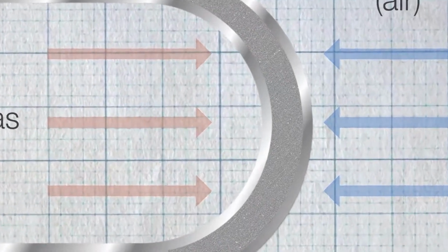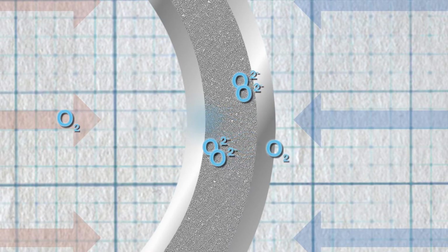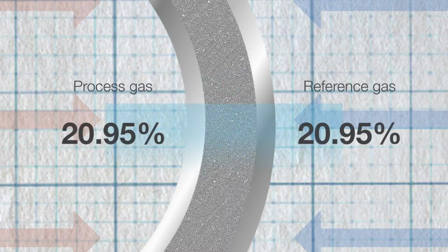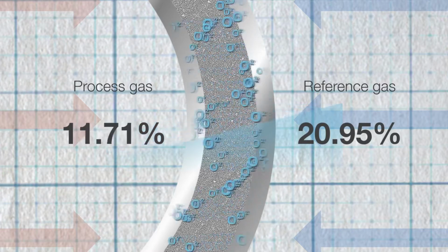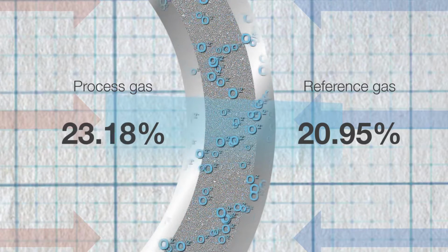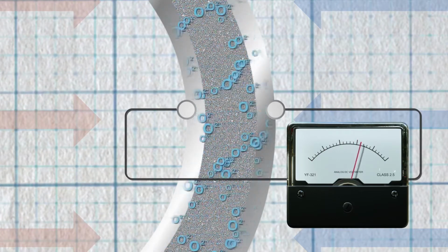When the concentration of oxygen is equal on each side, migration of the oxygen ions through the zirconia is zero. When concentrations differ, migration of the oxygen ions will increase as they try to re-establish equilibrium. The reaction at the two electrodes will differ, generating a corresponding potential difference. Using an appropriate device, this difference can be measured to produce a percentage oxygen concentration reading.